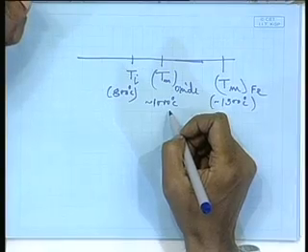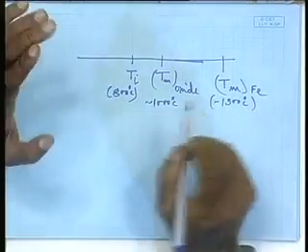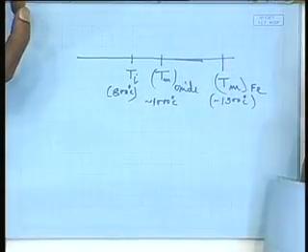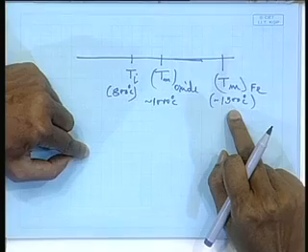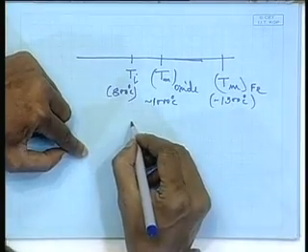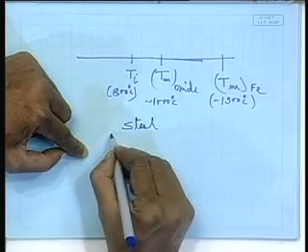It turns red hot, reddish color, because steel has a peculiar property. I mean, by seeing the color you can make out what temperature it is. At different temperature it exhibits different color. So, it becomes red hot, that is around 800 plus. So, you put in more oxygen and it starts cutting, right. Basically, then the temperature has gone up to around 1000, and the molten oxide is being thrown off. So, metal is not melted at all, its melting temperature is much above 1500. So, that is how steel is cut, right. That is pure oxyacetylene cutting.